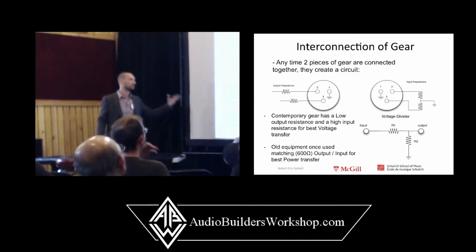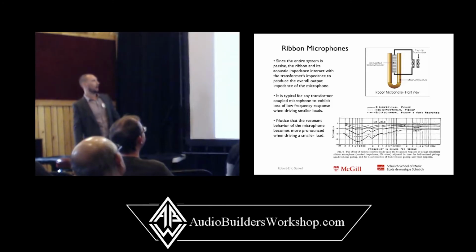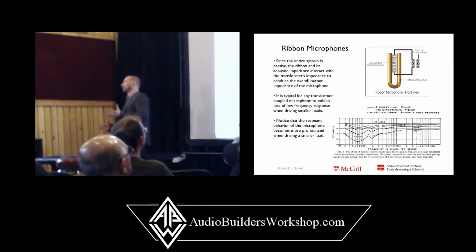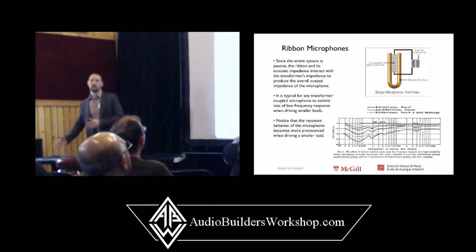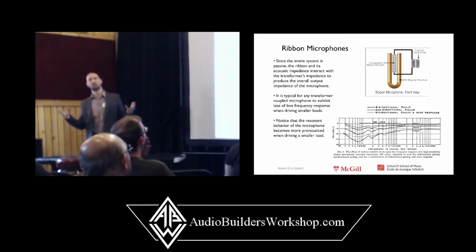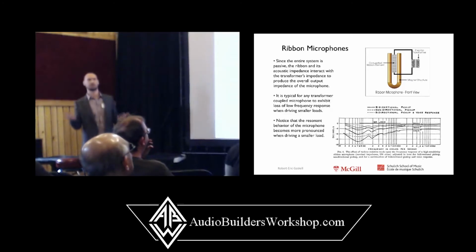Yeah, so when we talk about balanced equipment, this is just happening twice. We have output impedance that should be matched between pin 2 and 3, and a balanced input impedance that, again, should be matched between pin 2 and 3. But where this gets interesting is how the microphones will react to the load that they see.